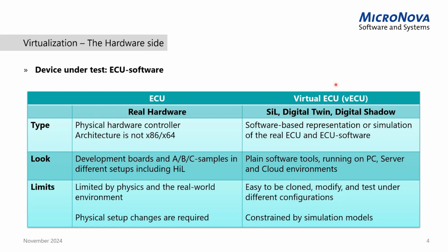It's basically a software-based representation or a simulation of the real ECU, and therefore the real ECU software that is our device under test. So the main point is it's entirely software-based, and so we've got the software tools running the simulation or running this ECU software, and they are running on a PC, server or any cloud environment there. The limits are, of course, it's constrained by the simulation models that are included in our simulation.